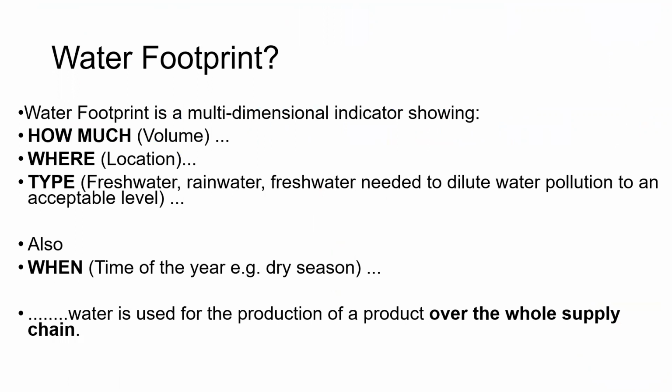So what about this water footprint? Basically, water footprint is about three things. One is the volume, meaning how much water is being utilized, or will be utilized, by a specific industry, or for domestic purposes, or other purposes like irrigation, dust suppression, floor washing, product washing, etc. The second important point is the location of that water. If we are using groundwater, the location of the area where you are going to abstract the water is very important, because nowadays CGWA permission is required for any quantity in any area in India to abstract water for industrial purposes.